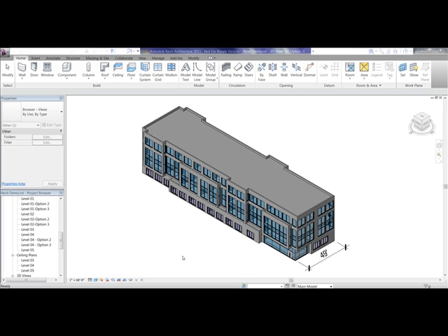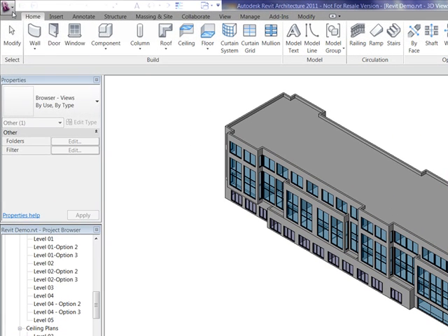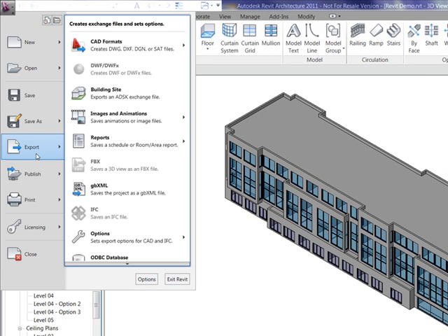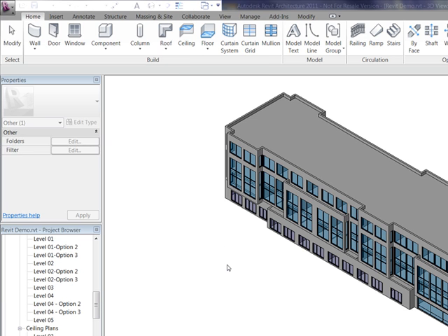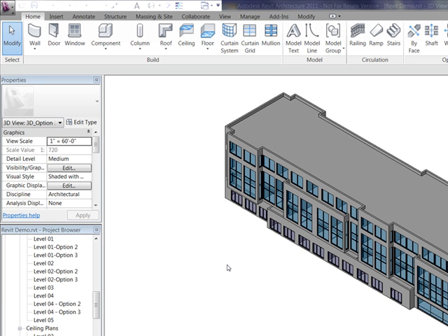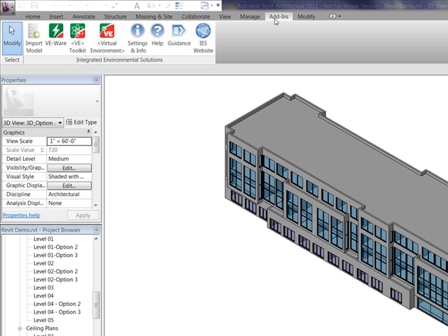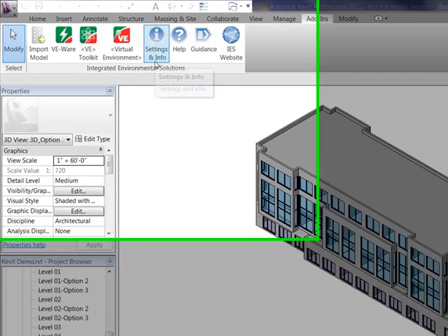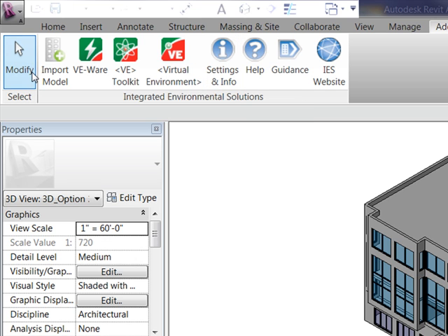So just to talk a little bit about our new Revit plugin that will help you bring geometry out of Revit through a GBXML format. This is similar in a way if you go to the drop-down menu here and go Export, File, GBXML. However, there are a few benefits to using our toolbar. If you go under the Add-ins tab, after you've installed it from our website, what you can do is preview your model much in the same way that you can when you actually go File and Export. But the benefit here is that we've actually added some new features that help heal your model.